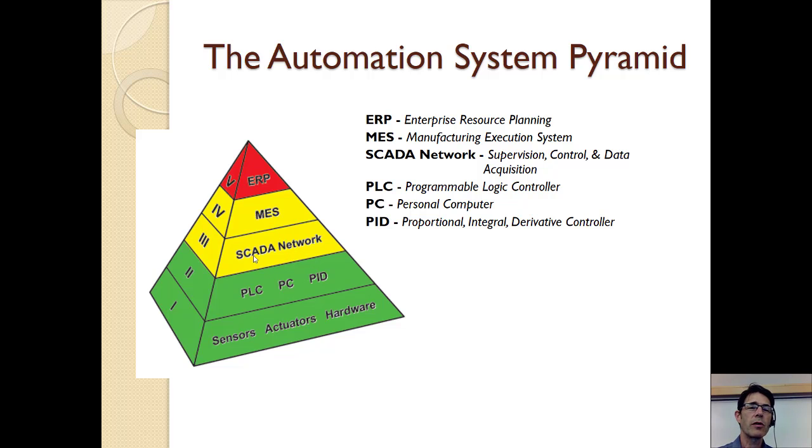So the simplest version of that would be like an Ethernet network. You've got Ethernet cables. Each PLC, for example, has an Ethernet connection and an IP address, and it ties back to a network switch, and a computer plugs into that switch. Now you are set up so that some designer can create some software that will then drive that system from a remote location or monitor it.